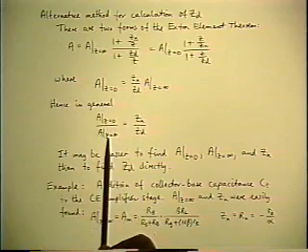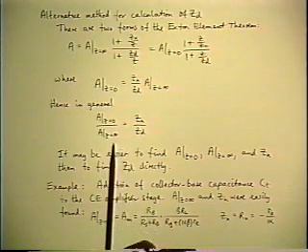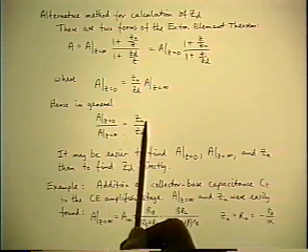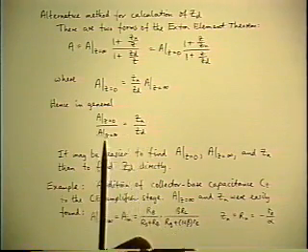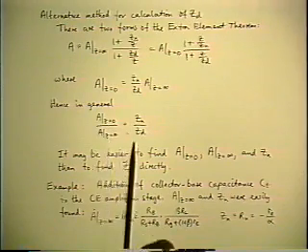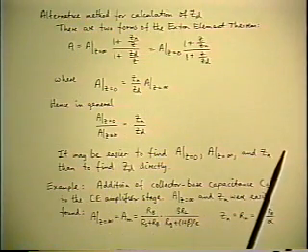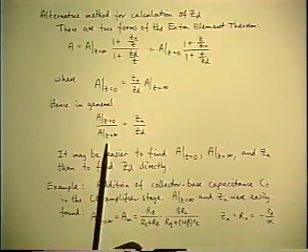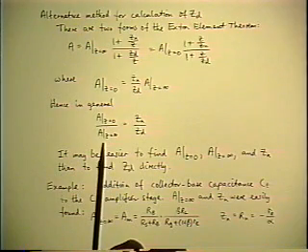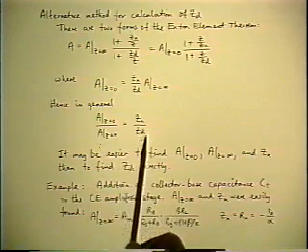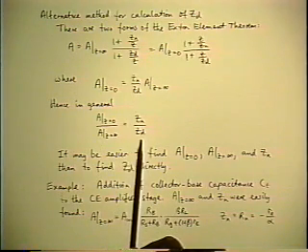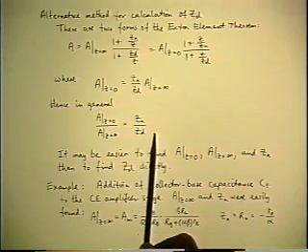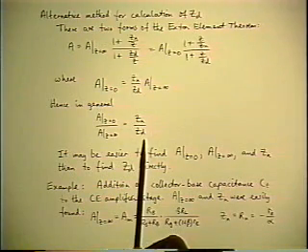So the ratio of the gain of the system when the element is zero to the gain when the same element is infinite is the ratio of the two driving point impedances seen by that element. It's sort of a redundancy relationship. Now, the way we've been applying the theorem is we know one of these gains, because that's where we start from with the original circuit. And then we calculated the two driving point impedances in order to determine the correction factor. We found that calculation of the Zn is always easy. Calculation of the Zd may get more difficult in more complicated cases.